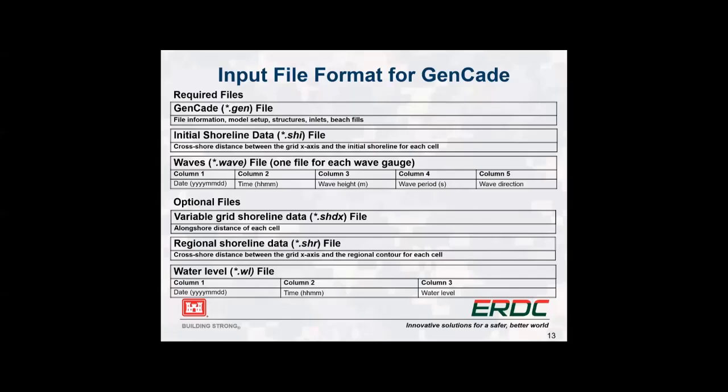And then the water level file, I don't see that used a lot. I think that's only needed if you have a variably transmitting breakwater. If you need those values, that's an additional file that's required.